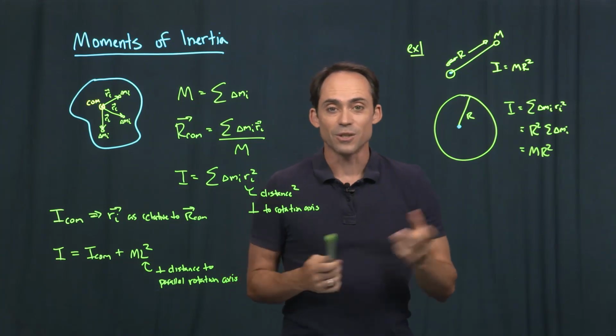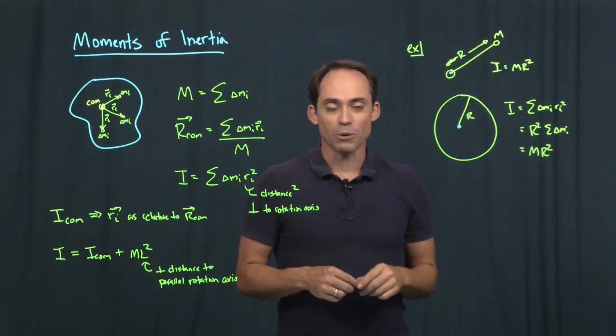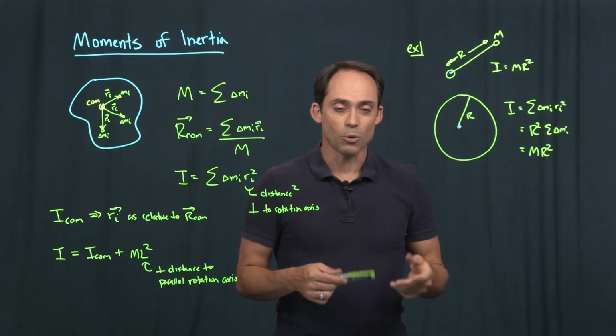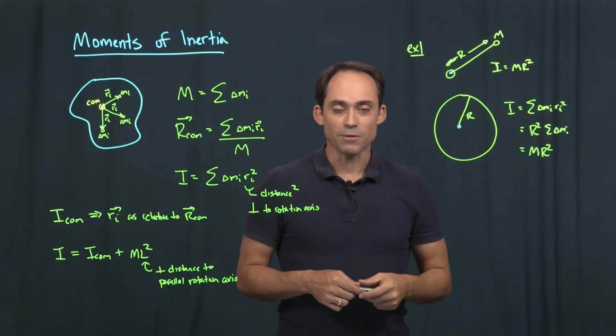which is identical to the moment of inertia of just this point mass that's swinging around by a string. We're going to see that symmetry again later on as we look at some more complicated shapes for moments of inertia. So as our first example, let's take a look at the moment of inertia of a solid disk. So this might be a frisbee or a plate, and we can build on our solutions based on what we've solved before for just the point mass and the hoop or ring.